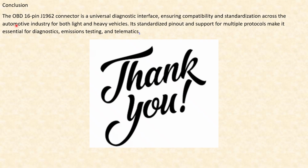So in conclusion, the OBD 16 pin J1962 connector is a universal diagnostic interface, ensuring compatibility and standardization across the automotive industry for both light and heavy vehicles. Its standardized pinout and support for multiple protocols make it essential for diagnostics, emission testing, and telematics. Okay, thank you.